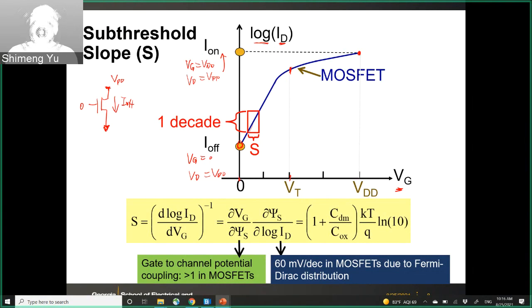Because you have to maintain those logic transistors, especially the SRAM, in this standby mode, and then you still have the current flowing from the VDD to the ground in the standby mode, even if the input is 0. But once you have the power supply on, then you have the leakage current, this I-off, and this is burning your power in the standby mode.